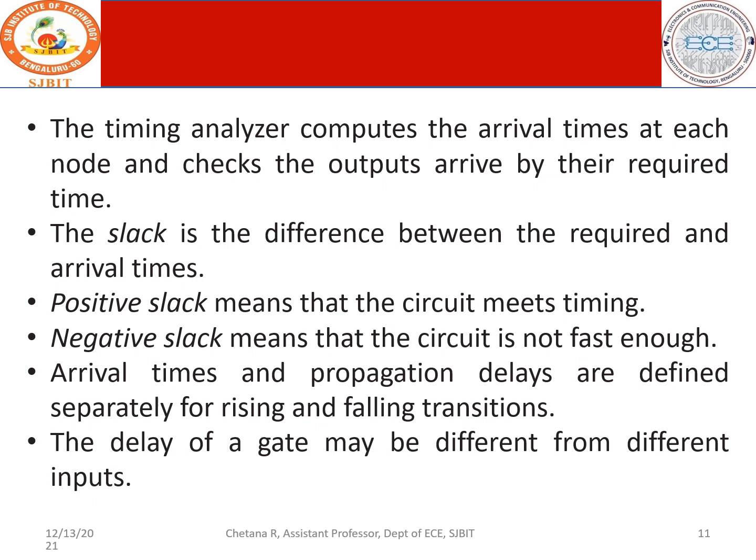So what exactly is the purpose of timing analyzer? Timing analyzer computes the arrival times at each node and checks the outputs arrive by their required time. If there is a delay in that particular path or in that particular node, then that can be rectified, or if that is really not required, that can be completely eliminated. This is how our design becomes better, or in other words our design is optimized. Therefore it is very much required for us to understand the arrival time.